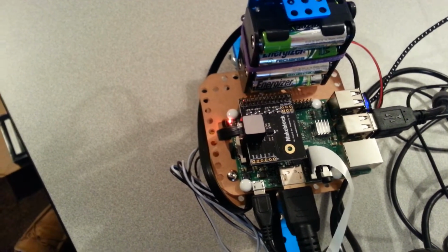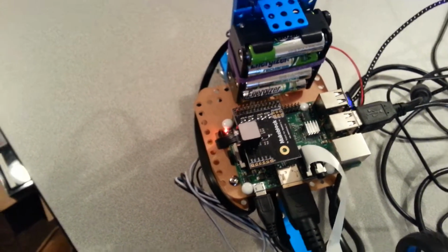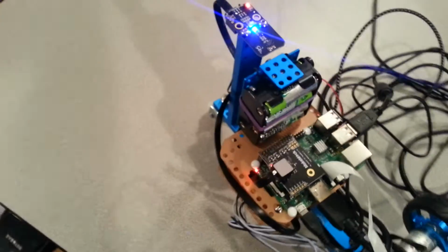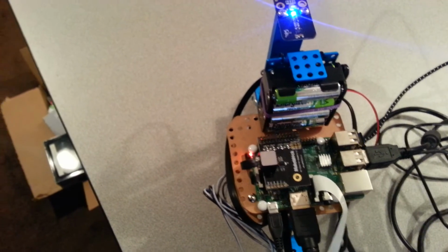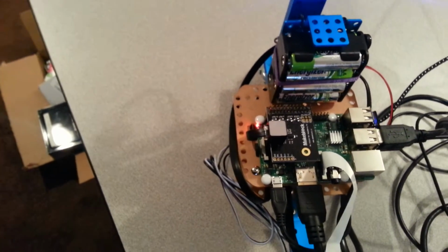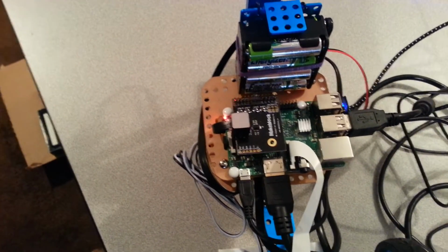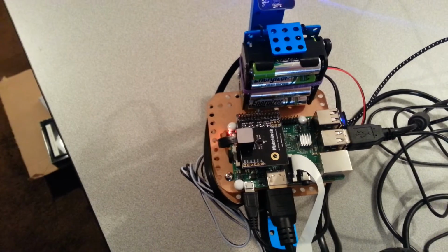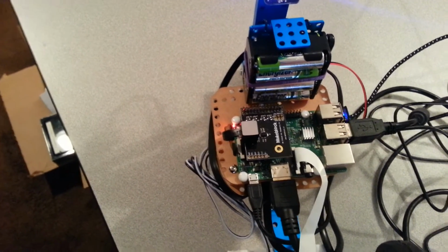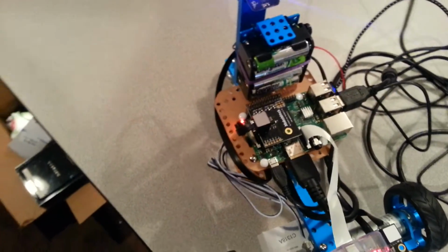One additional thing, this right here is a shield for hooking the Arduino to the Raspberry Pi, and it provides a serial interface. The built-in serial interface from MakeBlocks does not work. However, there are a couple of people who've done some work on building newer libraries, myself included, and it is a very convenient way of communicating between the two systems, but the default libraries don't work quite as advertised.